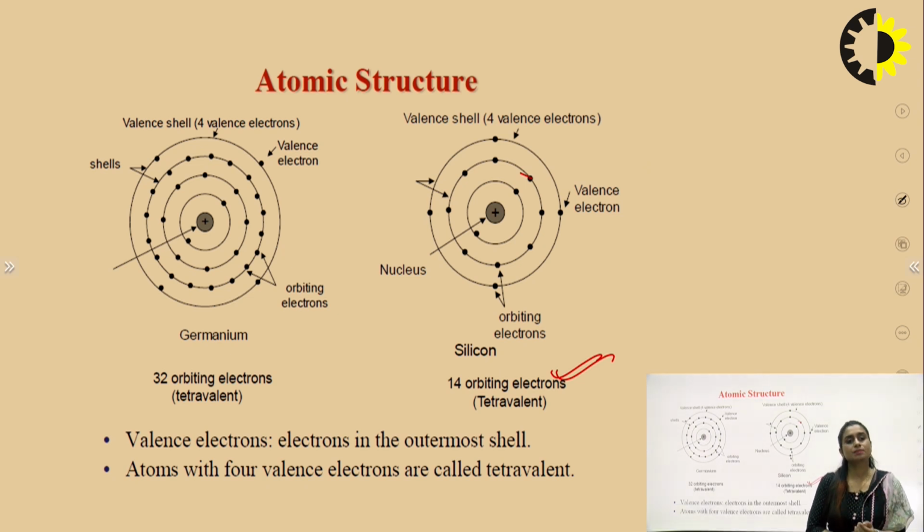If I increase the positive potential at the anode, electrons will move faster, they will be accelerated. If I decrease the potential at the positive end or the anode, their speed will be reduced or they will be decelerated. This variation in velocity and the movement of electrons will generate current. If electrons are moving from cathode to anode, there will be flow of current from anode to cathode.